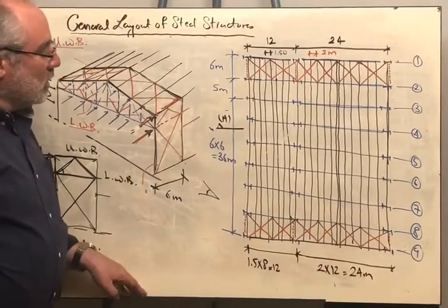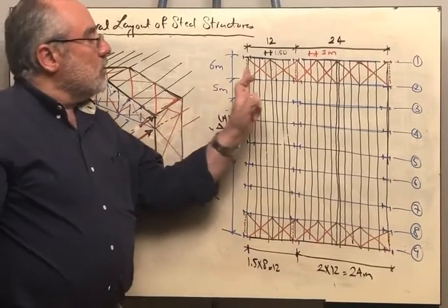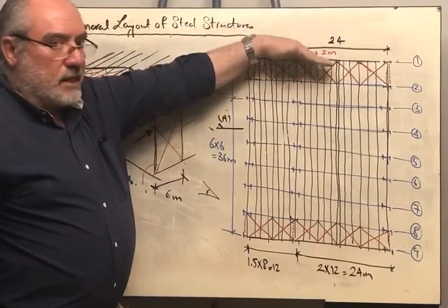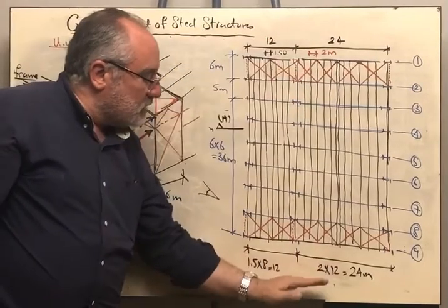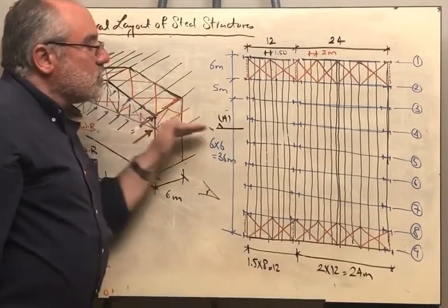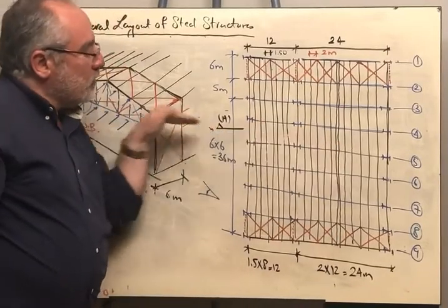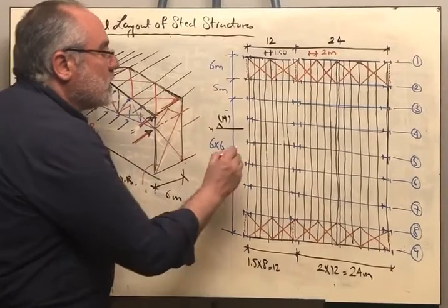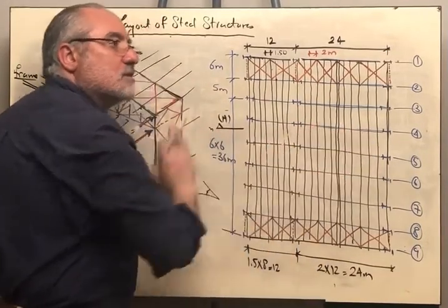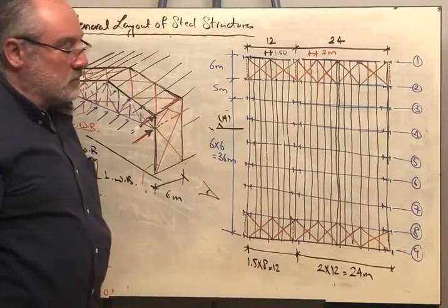Very good. Now, this bracing is supposed to resist the wind loads blowing on this side, and this bracing is supposed to resist the wind loads blowing on this side. What if the wind is applied in this direction? If the wind is applied in this direction, it will be supported by the main system itself because it is parallel to the main system, which is a 2-dimensional system.